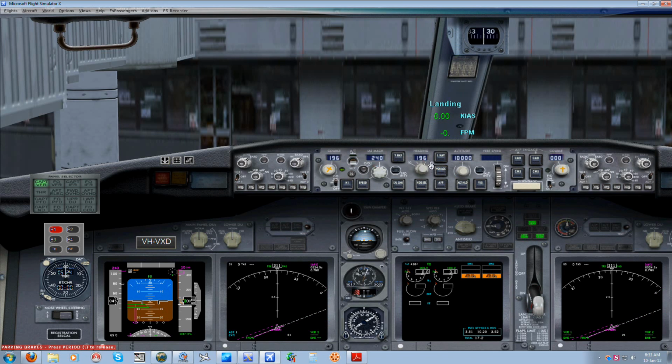Now altitude, we select our altitude. We've programmed our FMC for 35,000. So all we do is right mouse button all the way up to 35,000. We can go straight up, because the FMC will actually do a step climb for us. So the FMC will control the whole aircraft through the whole flight. It will maintain the airspeed, the heading, and the altitude for us, and it will just do step climb all the way up to 35,000.